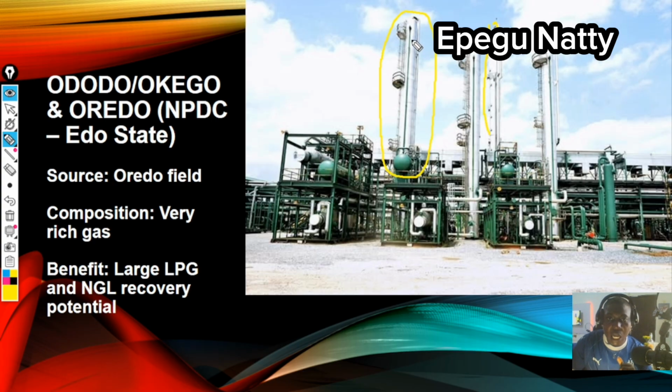Now your de-ethanizer has, at the top, it goes down to what you call reflux condenser, right? So this reflux condenser condenses and then sends it to your reflux drum. So your reflux drum now sends the gas back to the tower, where it stabilizes the top of the column, and a lot of heat exchanging takes place inside. The colder one will be coming down, exchanging heat with what is inside to stabilize the column.